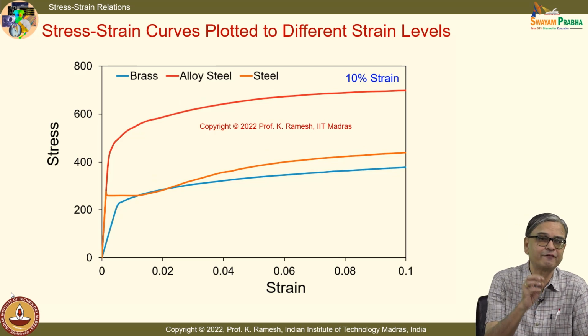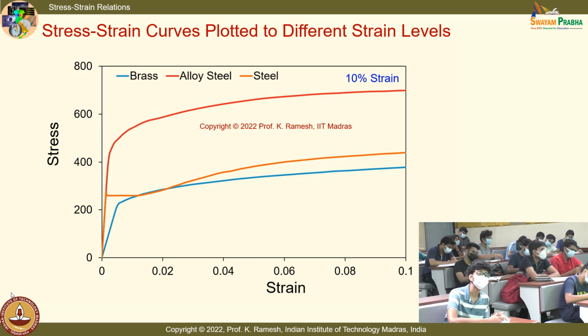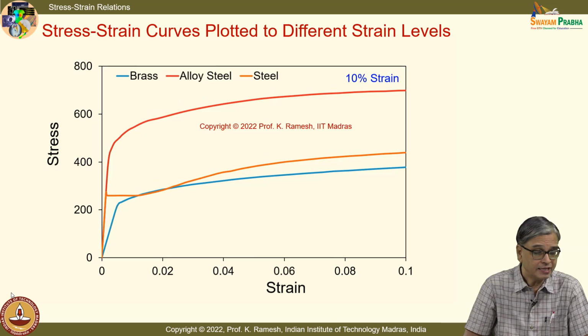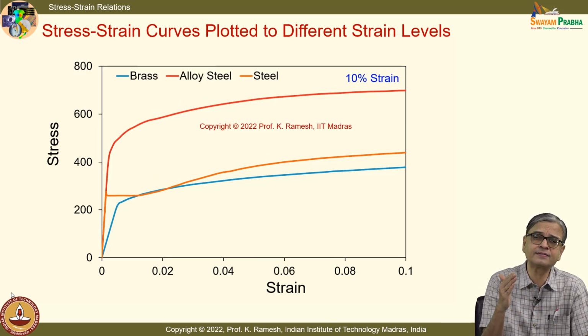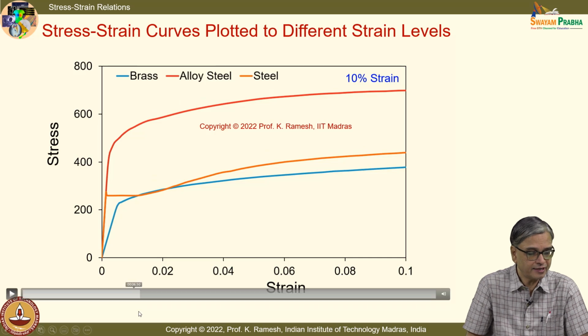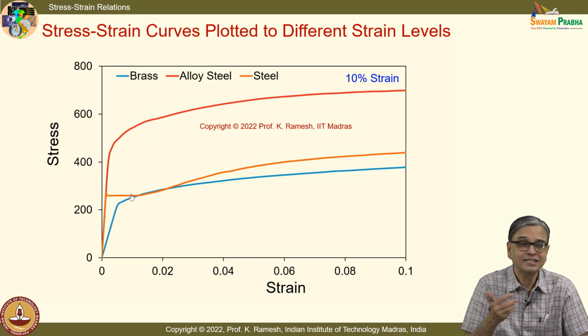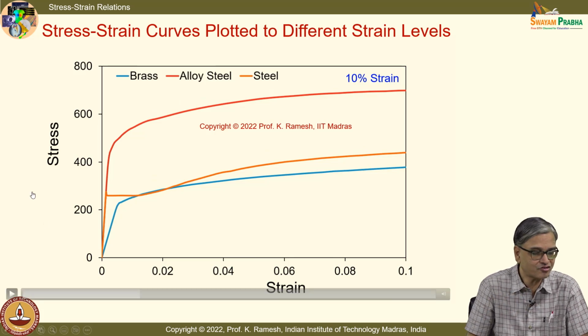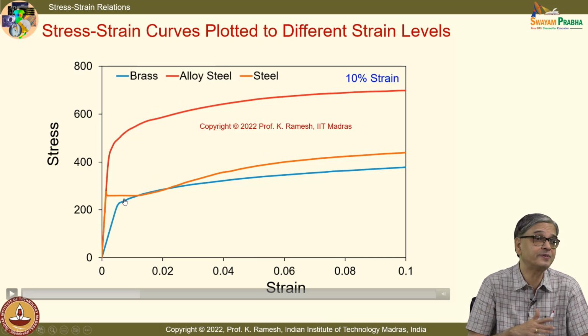Likewise, we will have a few steps. I want you to draw it and keep it for your reference. This explains many of the simplistic models that we want to adapt to characterize a material. For example, for the mild steel, I have a straight portion. If you ignore this small kink, it becomes horizontal. Don't you see that? That was not very clear when we looked at 40% strain. So, I have a straight line followed by a horizontal line. That kind of an approximation is also made.